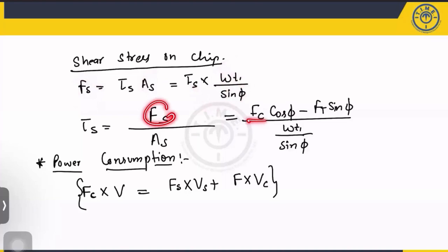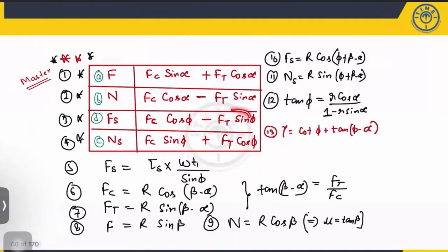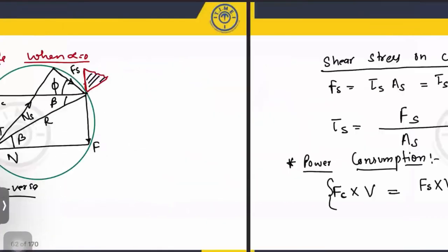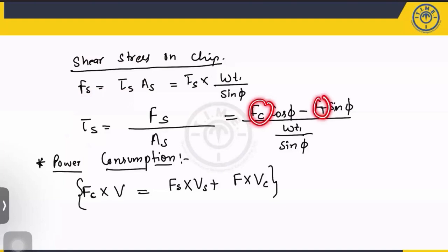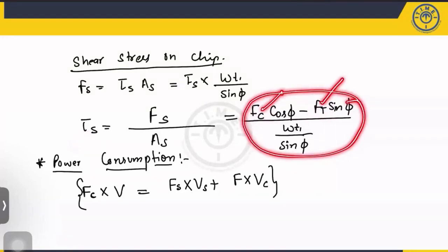And what is the shear force? The shear force, if you consider from this master table, this one is the shear force. If you divide it with the shear area, then you can calculate the shear strength. That means sometimes they ask what is the shear force value by giving the shear strength. Sometimes they give the cutting and thrust force, then you have to calculate the shear stress. So you have to use this particular relation. Cutting force and thrust force is given.